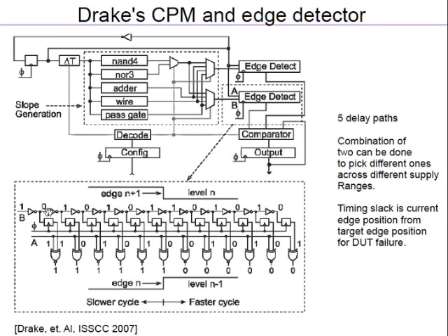Instead of using a buffer, the previous work by Nakai used a buffer, which means 2 inverters. A buffer is non-inverting, whereas here they have used a simple inverter. So you see how many buffers it has crossed. You can measure the delay in units of buffers, in this case, units of inverters. So your inverter becomes a unit for measurement of delay.